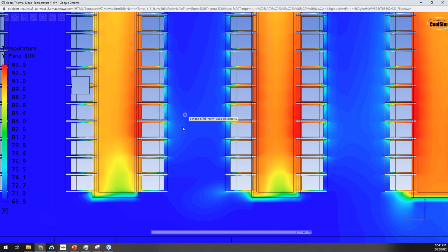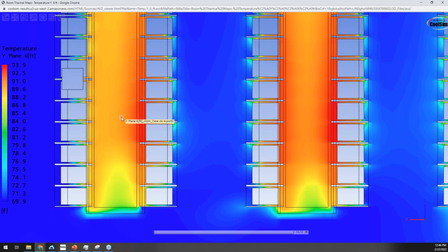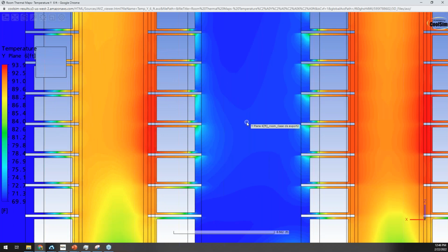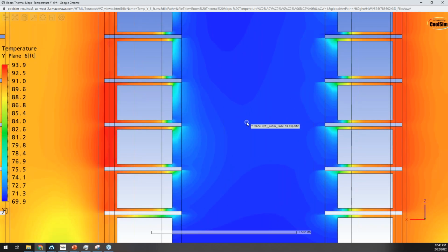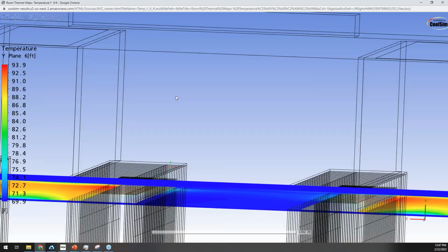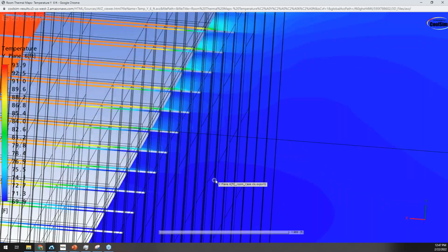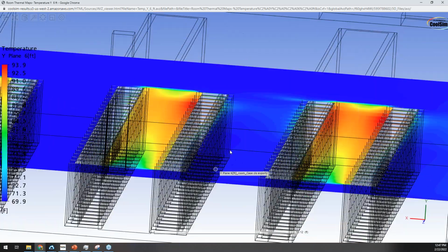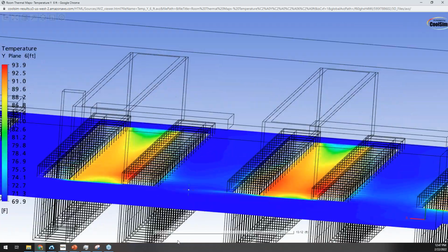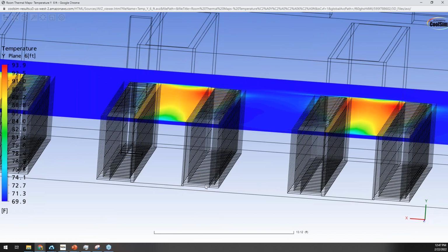So the low pressure caused by the high velocity in the front of these servers, compared to the higher pressure here, because the air flows are banging into each other and the velocities are going to zero and the pressures are going up, is causing leakage through the rack rails. Now, to prevent that, you've got to pay attention to rack rails. You've got to seal them, particularly under the racks. This one often gets overlooked, down below the rack on the floor. People don't pay much attention to what's going on down at the floor. Under these racks can be problematic and cause issues.